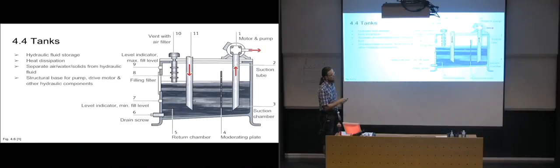And also, if the opposite happens, much of the fluid that's in the system is returned to the tank, it's getting filled up again, then you need to let the trapped air escape, or else you're going to create air under pressure in there. You don't want that in there. And that's why it has a filter on it also, because you want to avoid pulling in dust particles that will mix with your fluid.